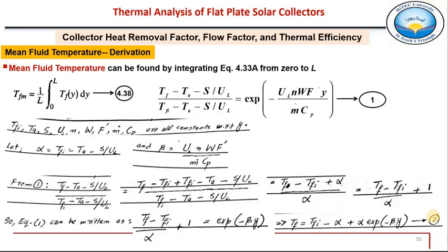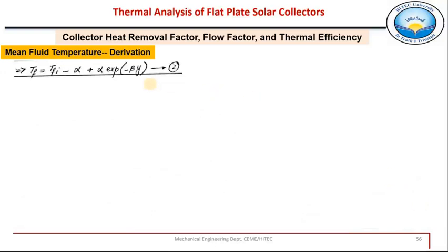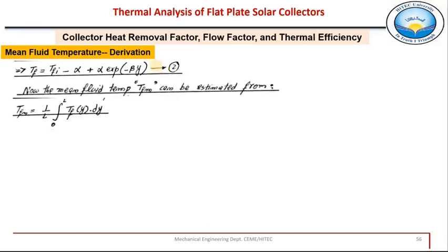So now the mean fluid temperature, we will proceed further from this equation 2 onwards to find out the mean fluid temperature. So now the mean fluid temperature TFM can be estimated from this equation, right? And we already know this is the general equation to calculate the TFM, where TF at any y is this equation 2, right? So now we can put this equation of TF here, right?